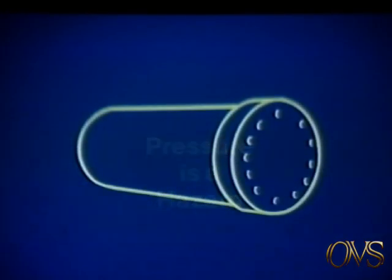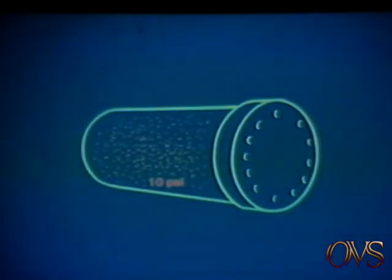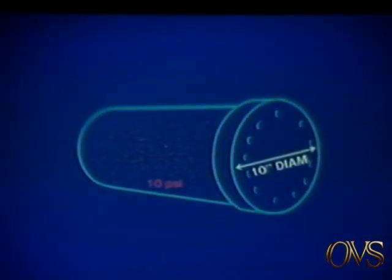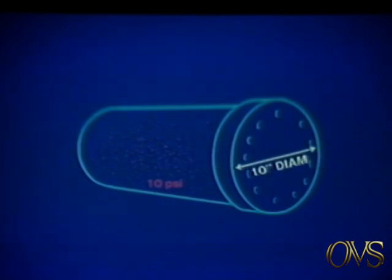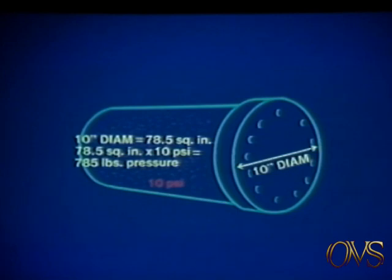Simple pressure on the line is another major danger to personnel. For example, while 10 pounds per square inch doesn't seem like much compared to normal line pressures, consider what happens when 10 psi is standing behind a 10-inch diameter blind flange. There is 78.5 square inches of area on the back of that blind flange. Each square inch has 10 pounds of pressure behind it. That's 785 pounds of force held captive by the flange bolts.